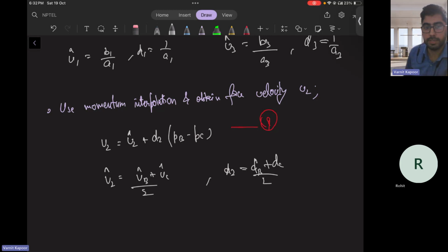So in the context of staggered meshes, we were discretizing the continuity equation on the pressure cells. Now in the context of collocated, you will discretize both the momentum equation and continuity equation always on the single cell, that is the primary cell, which are basically cell B and cell C. So you do not have any other cell to discretize. So discretize the continuity equation on cell B.